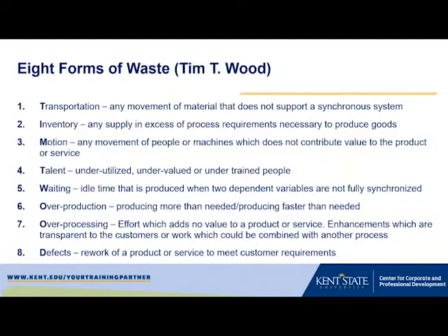So an easy example of that to me is if you have to, let's say, heat treat or anneal some metal parts to remove stresses, and that annealing process should be 4 hours long, and you leave those parts in the furnace for 6 hours, then you've overprocessed those parts. They're still good, but you didn't need those extra 2 hours, and that's time you're never going to get back. It's non-value added time. It did not provide any value to the customer.